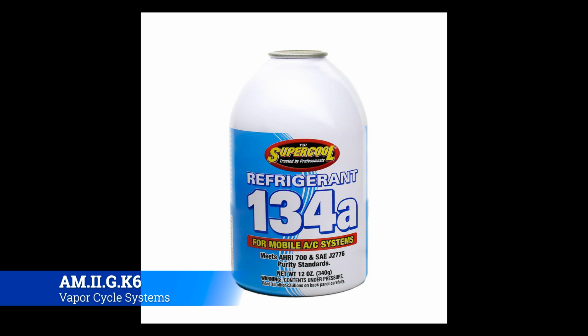The amount of refrigerant required for any system is measured in pounds, so that's something to remember. Follow the manufacturer service data, and you charge the system to the level specified, only when approved refrigerant is from a known source. So don't be pulling it from one plane to put in another plane or anything like that. Also, in order to handle this, you're going to have an EPA certification.